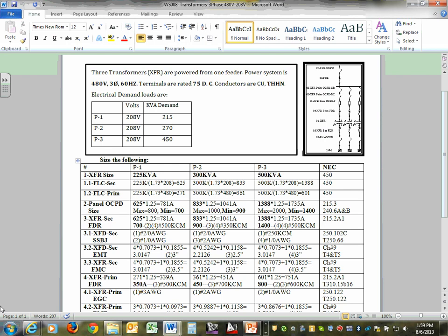And it could happen. So then I took 3 examples, the same thing. I have a manufacturing floor, and I did the kVA calculation on my loads. You have to start with the loads. I always emphasize, guys, your load is your reference point. If you don't know, you make assumptions: 225 amp panel, that's good enough, 100 amp panel, but if you start with the square foot of the building and the loads.